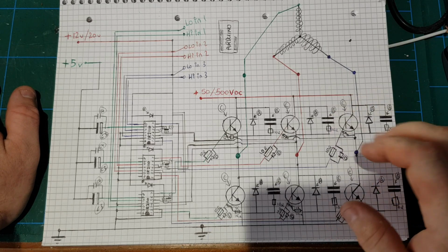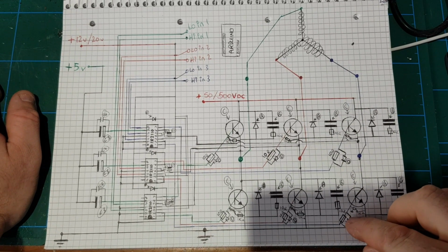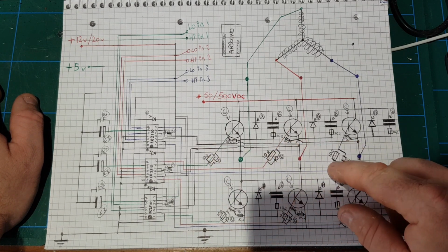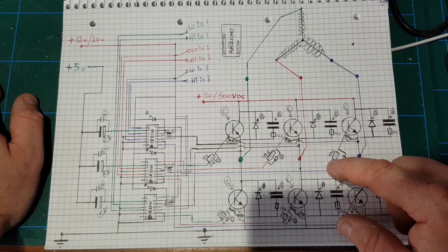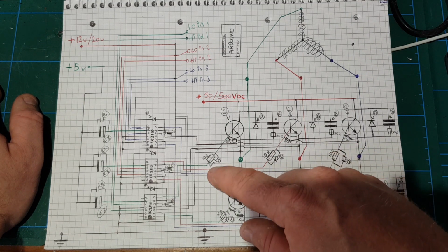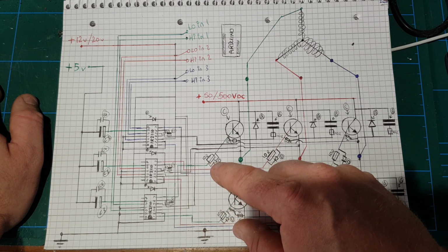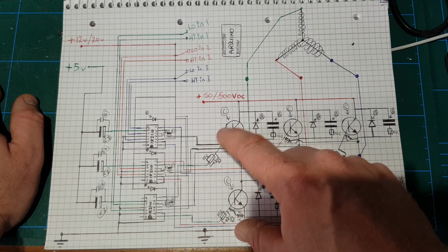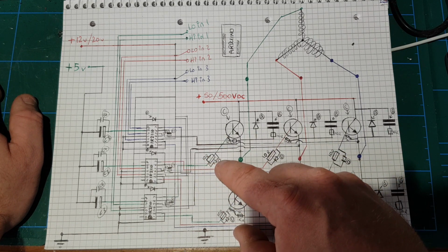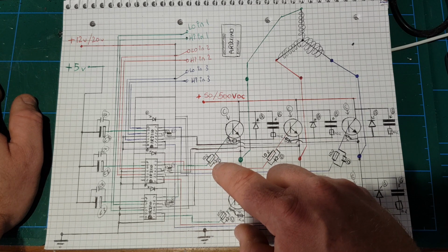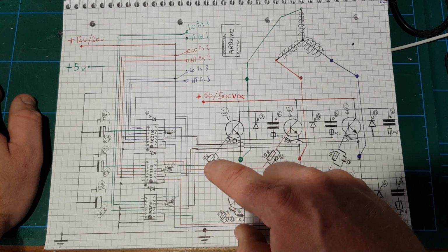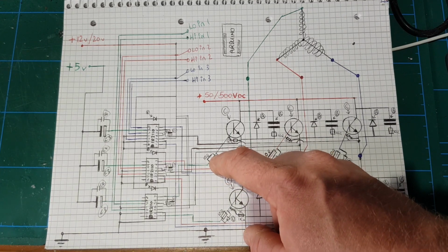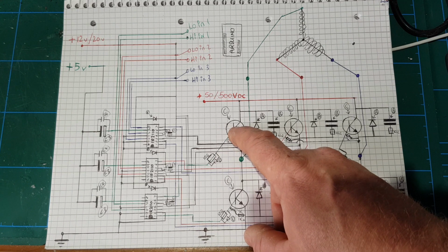So that's your driver circuit. These are your 10 ohm resistors that I was talking about, with your diodes. So what these diodes will do, as the chip turns on the gate, the diode is in reverse bias mode, so it won't pass any current. The switch on of the gate will be handled via this resistor, so it will limit the amount of current that can be passed into this gate.